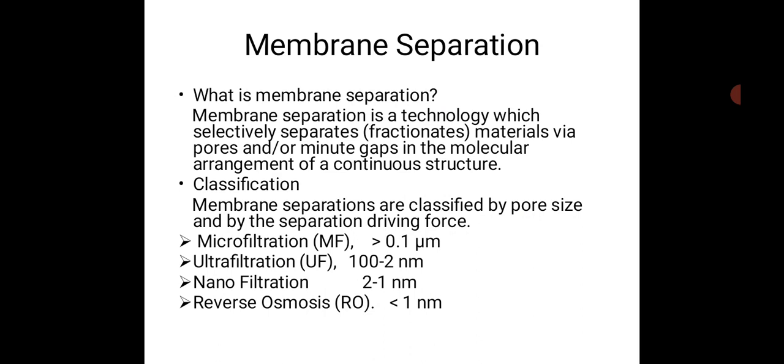If the pore size is greater than 0.1 micrometer, it is called microfiltration. If it is between 100 to 2 nanometer, it is called ultrafiltration. If it is between 2 to 1 nanometer, it is nanofiltration. Less than 1 nanometer, it is called reverse osmosis.